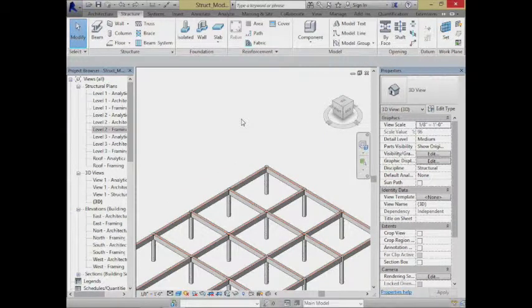Okay, just a few final things to get you going. Now, these big old bays that we've set up right here are currently about 30 by 30. And if I reinforce the slab appropriately, I might be able to go ahead and have a 30 by 30 bay. But I might want to put some intermediate beams in there to help support that, where these bigger beams are girders. And then I'll have smaller beams, which I'll call joists, that run between them.